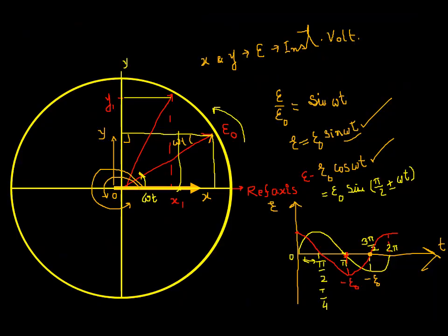This is known as a phasor diagram. Check it out. Actually, a phasor is a rotating vector. You can see at different instants, when the voltage phasor reaches some position, the perpendicular dropped on the x-axis, which is called the reference axis, and on the y-axis gives their instantaneous values.